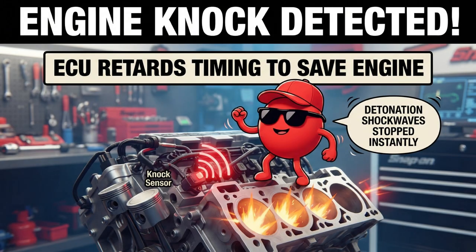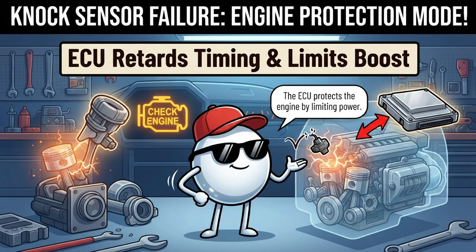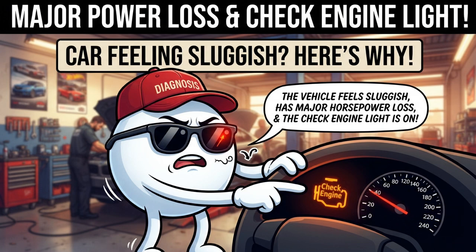When the knock sensor detects these specific pre-ignition frequency spikes, it sends an immediate signal to the ECU. Within milliseconds, the computer retards ignition timing, stopping the destructive shockwave before internal hardware gives way. If a knock sensor fails due to internal corrosion or damaged wiring, the computer can no longer detect pre-ignition. To protect the engine from destroying itself, the ECU permanently retards ignition timing and limits turbocharger boost pressure. The vehicle will instantly feel sluggish, suffer a major loss in horsepower, and illuminate a persistent check engine light.